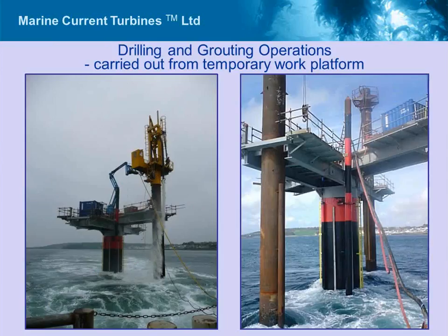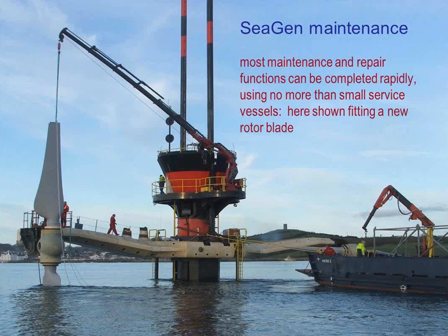So during the installation process, we used the structure to drill the pin piles into the seabed. As you can see on the left-hand side, the yellow structure is a pile-top drilling rig sitting on top of a conductor tube. The pin piles, like I say, were about 1 meter in diameter and embedded in the seabed 7 or 8 meters. We managed to do the drilling of each pin pile in about 8 to 12 hours. The pins were then just dropped into the holes and grouted into position.